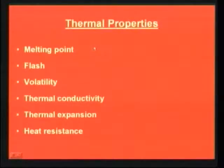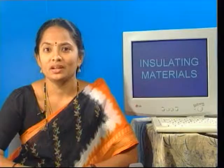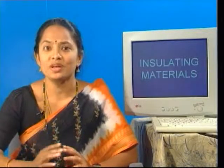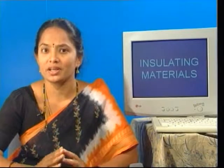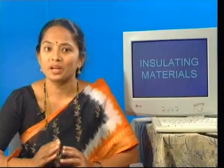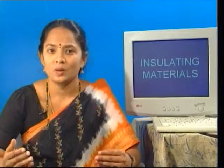The next property is volatility. A volatile material cannot act as a good insulator. When trapped gas is evolved from a volatile insulating material subjected to voltage stress, the breakdown of insulation is accelerated. Hence, the material used for insulation should not exhibit volatile property.